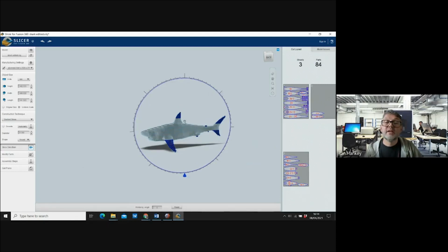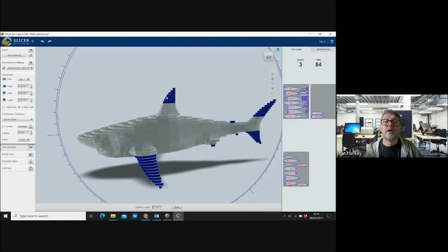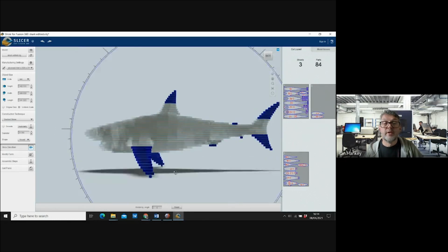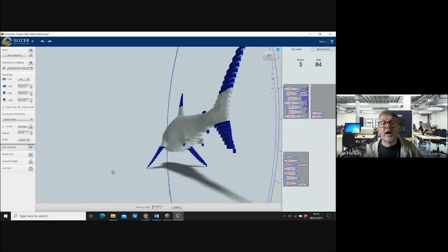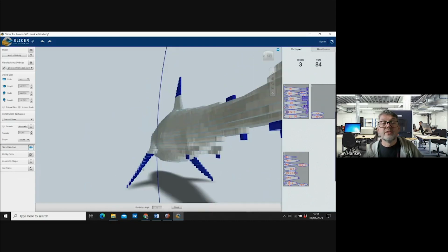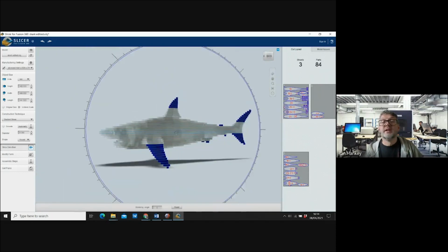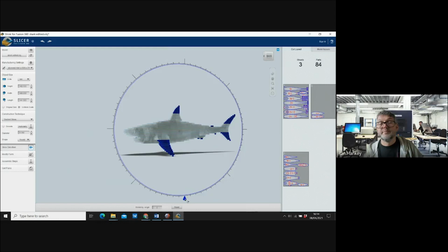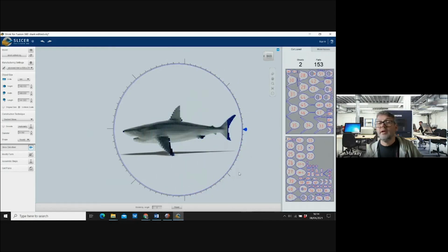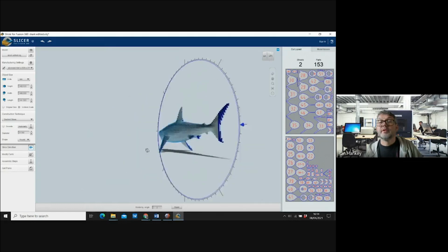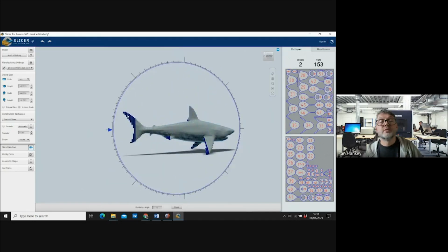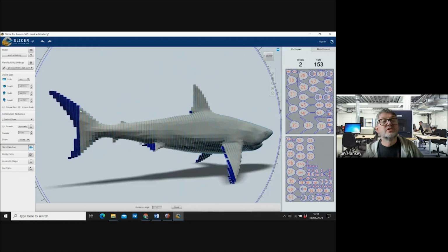And again, we seem to have an issue with the top parts here, and I'm not quite sure. You can probably see why here. They're stepped a little bit too much, perhaps. So it's registering that as problematic. So I might change that background again. And the slices are now going through there. Everything's happy with that. There's no kind of major problems. It's showing a bit of a blue outline, but it's still a darker color.